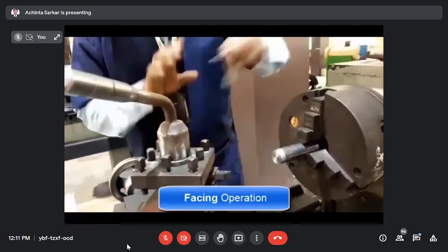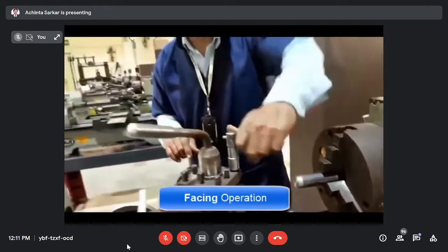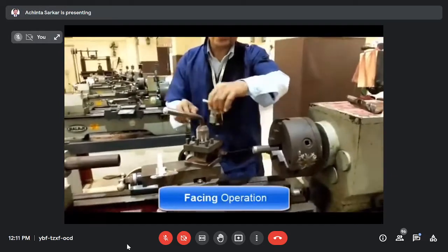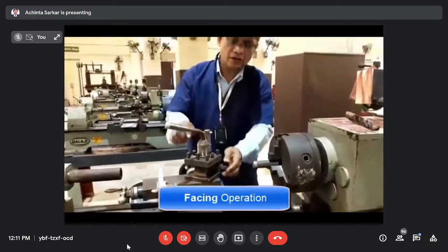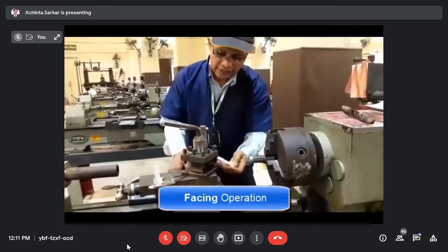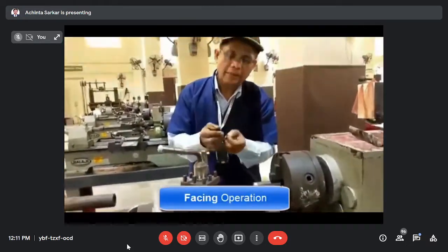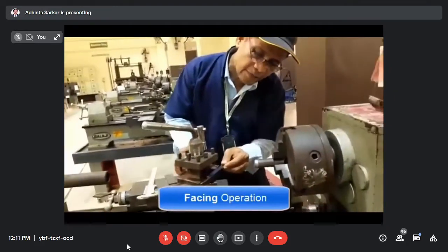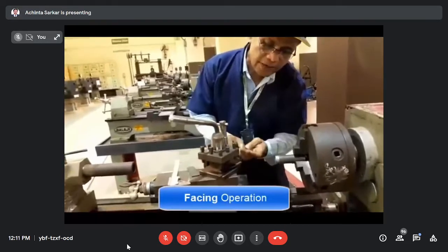That's why again just loosen the cutting tool, and you have to set the cutting edge or cutting point of the cutting tool properly to the center of the workpiece. This way, I am adjusting the thickness of the packing and setting it under the tool properly.